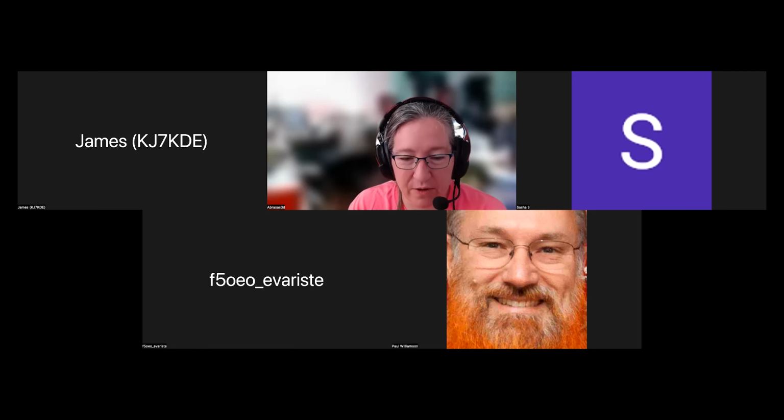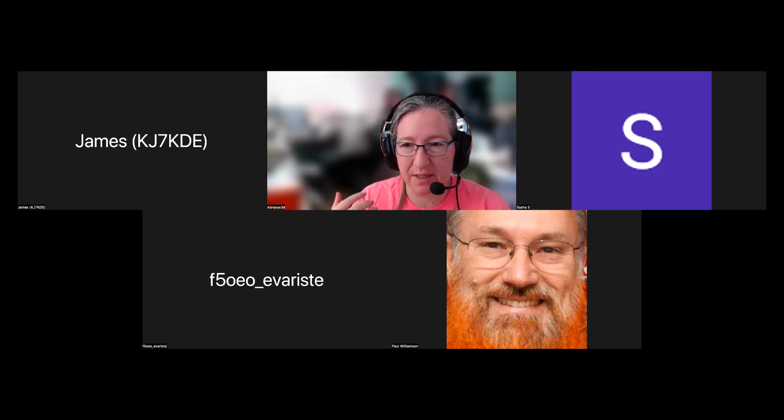Right, I'm with you and understand. At least the old way of doing it seemed to be to set it up using the transceiver evaluation software, the TES software, set it all in there, and then you get this C file or Python, either way, an export from TES, and that was part of your code. But now we want to use IIO, so there has to be something in IIO to set all of these values. I'll do all I can to figure out what the right way is. And of course, if anybody watching this knows, please help us out, and we'll be able to make quicker progress.